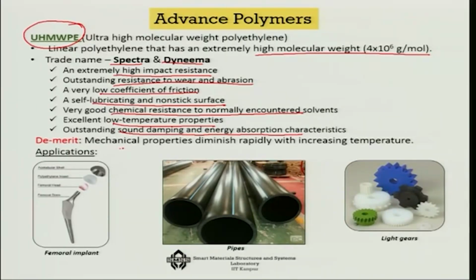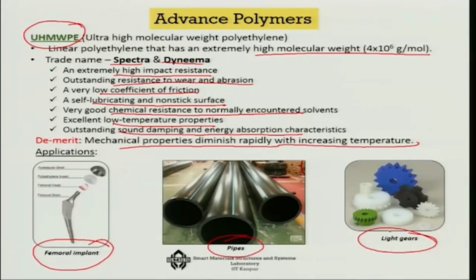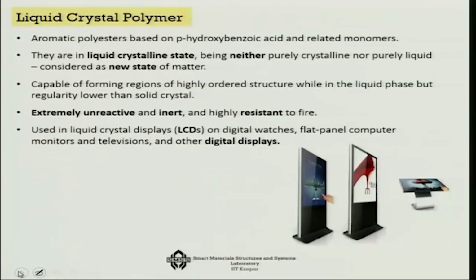Only thing is that their mechanical properties diminish rapidly with increasing temperature, because they are linear polymers. So they are susceptible to, as I told you, creep like problems, but if the temperature change is not very high, then they have excellent properties. They are used in femoral implants, pipes, light gears in Legos, etc. That is one example of advanced polymers.